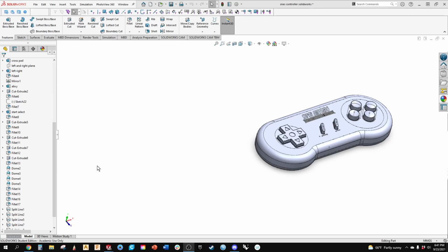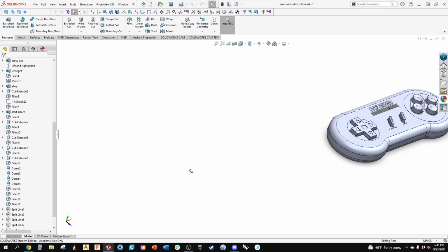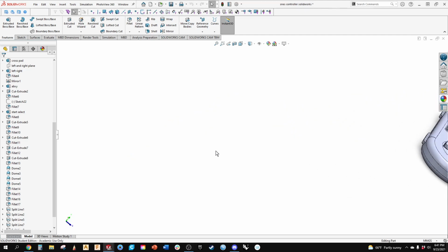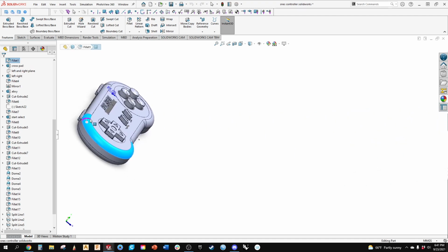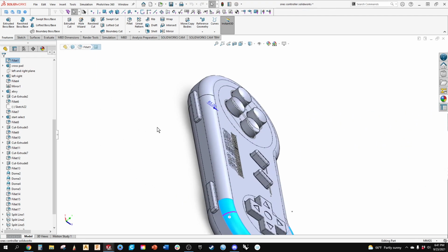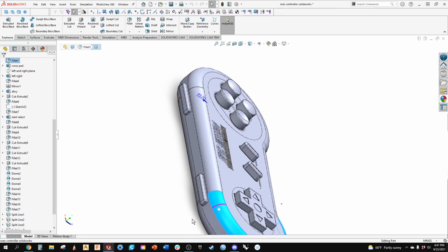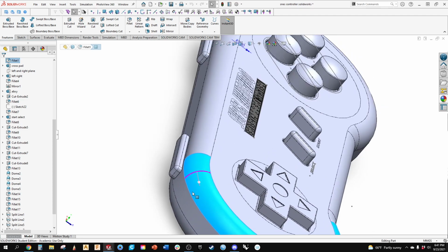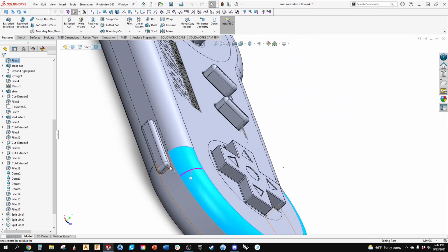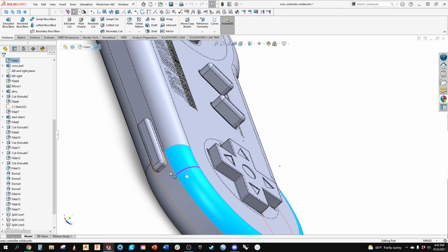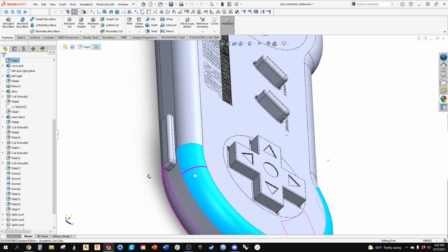Okay, Haley, let's take a quick look at your model here. The first approach is for the part line around the buttons. One of the things that I think is going to help is where you fused these in, or merged them. What we want to do is get that simulated part line around there, or that gap like you did in this area.